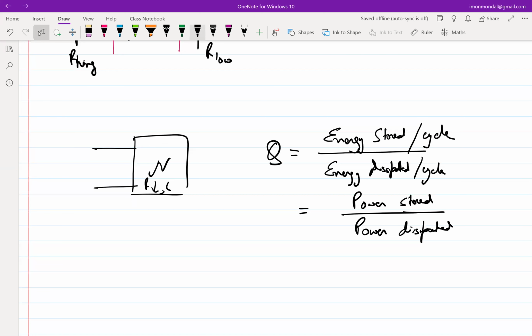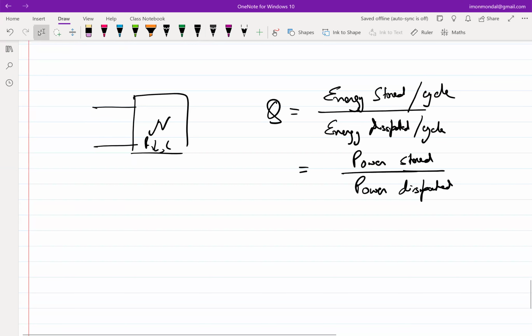If you do phasors, it doesn't really matter. In a very simplistic way, if I have an inductor with a resistance associated with it, RS is a series resistance associated with the inductor, because an inductor is ultimately a piece of metal. And in an IC, the metal resistances are not as low as you get in an off-chip interface. So in an IC, almost invariably, the losses of passives are dominated by that of the inductor. But we'll do both, the capacitor and the inductor.